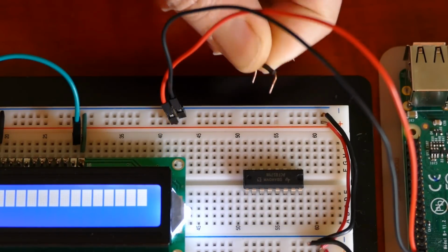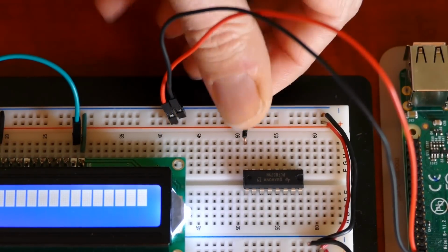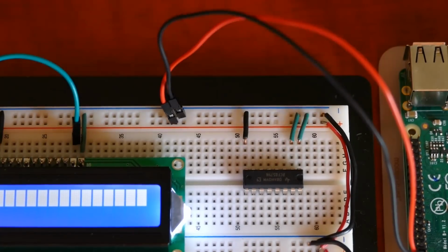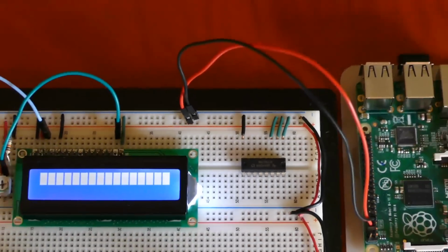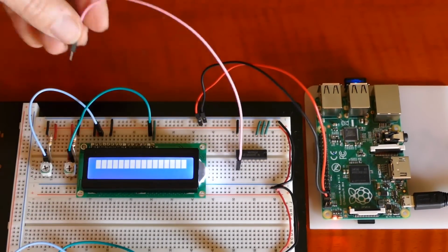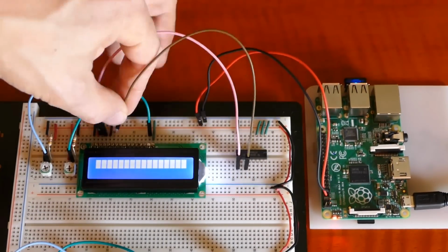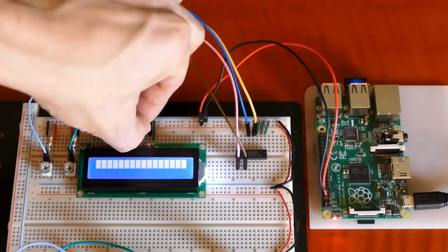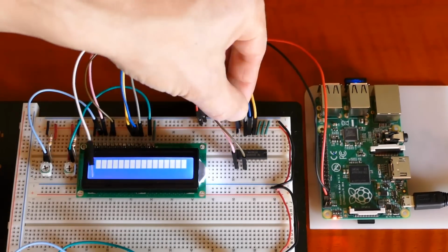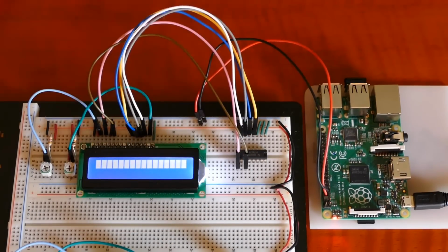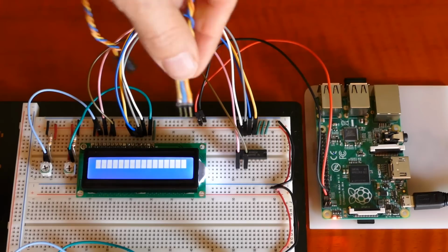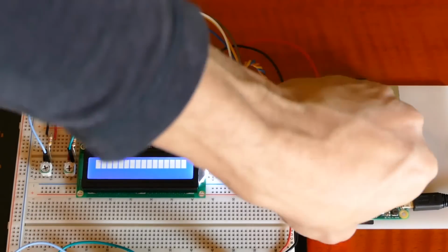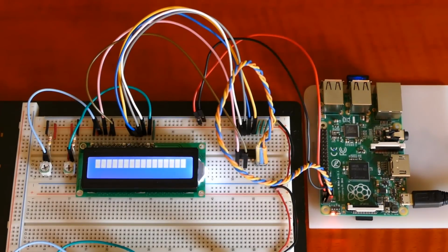On the breadboard, I have a PCF8574. I connect the ground pin to the ground rail, which is common to the Pi. I'll ground the 3 address pins to set the hex address. Each expander on the I2C bus requires a unique address. I connect P4 to RS, P6 to Enable, P0 to D4, P1 to D5, P2 to D6, and P3 to D7. Since the 3.3 volt SDA and SCL pins line up on both the Pi and the expander, I'll use a 3-pin jumper to connect them. That's all it takes.